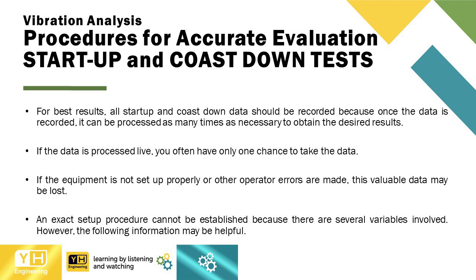For best results, all startup and coast down data should be recorded because once the data is recorded, it can be processed as many times as necessary to obtain the desired results. If the data is processed live, you often have only one chance to take the data. If the equipment is not set up properly or other operator errors are made, this valuable data may be lost.